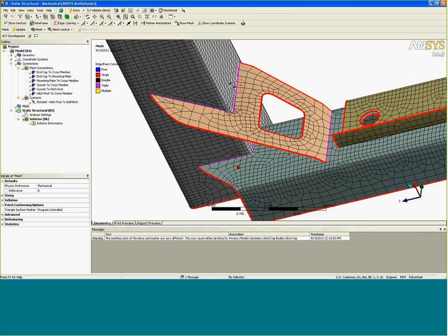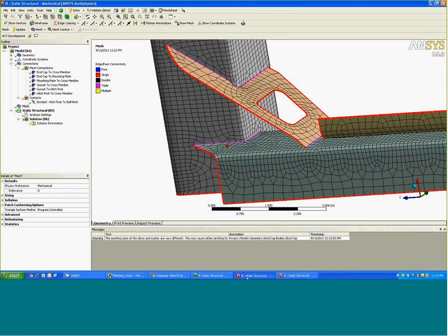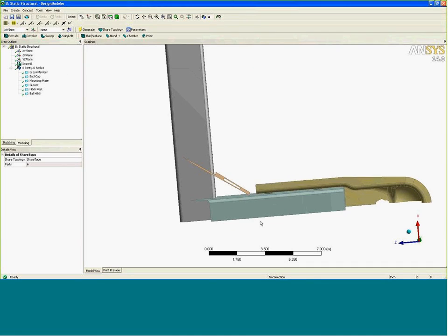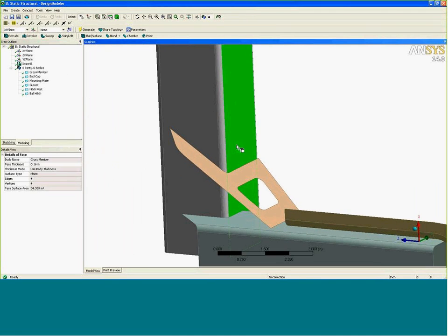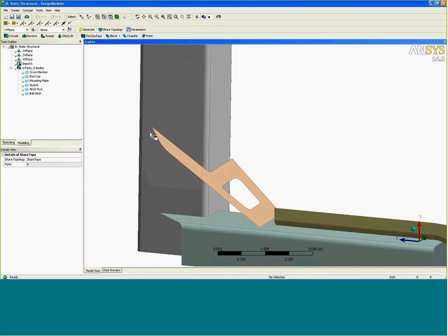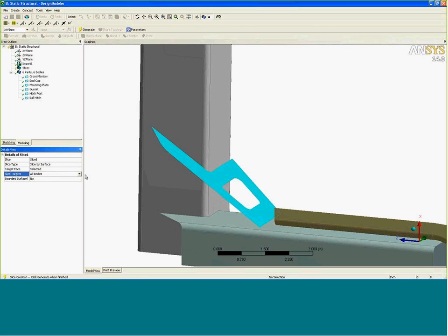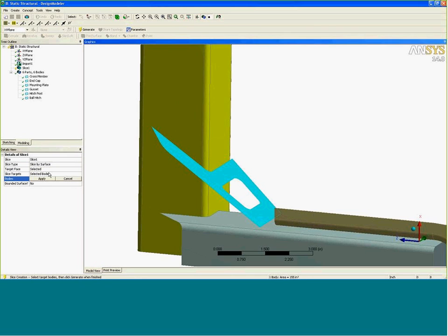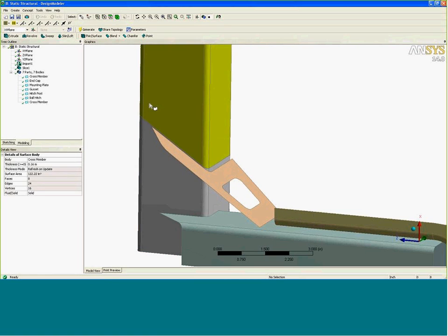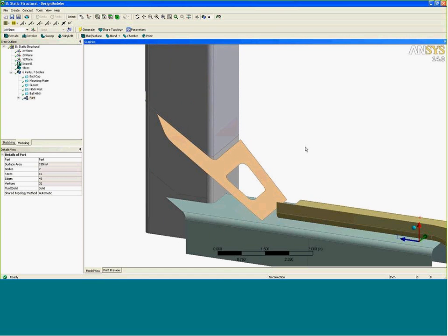So let's fix up this location in here, because we could make this a little bit better. I'll adjust the geometry a little bit. In DesignModeler, I have one big long surface that goes through here. This could be meshed freely however we would like. So if I go in and just slice this body, slice this surface right here, it'll put a nice split along here, and then I just form a part. So that's a continuous mesh, not an edge that will show up in here.